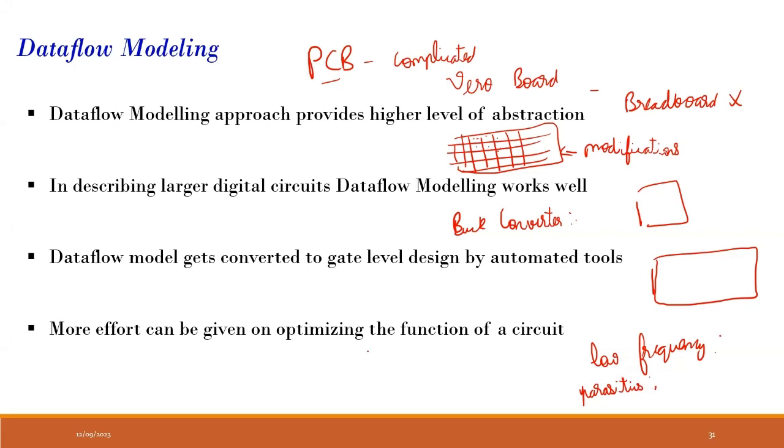Because if your objective is to learn, to implement these codes and logic, the board is secondary. The board is where you're testing it. The main thing is you want to learn your codes and logic and check whether they are working. So for that, buy a Vero board, a MOSFET, a gate driver, and resistors, capacitors, inductors as per your requirement.